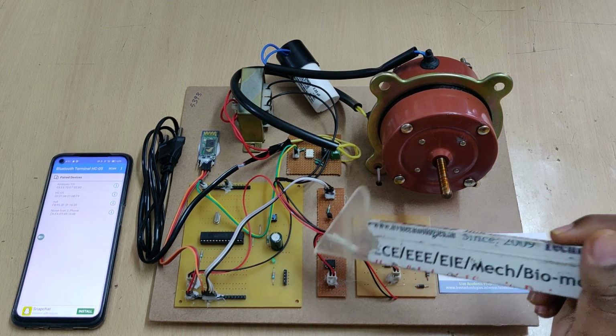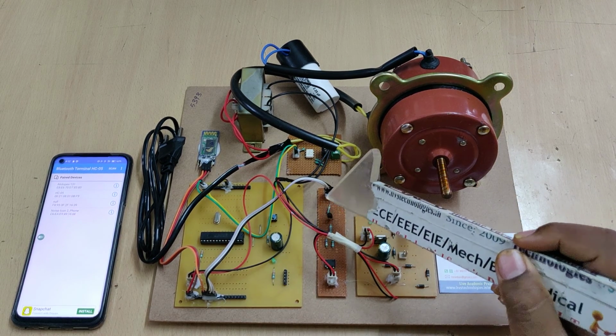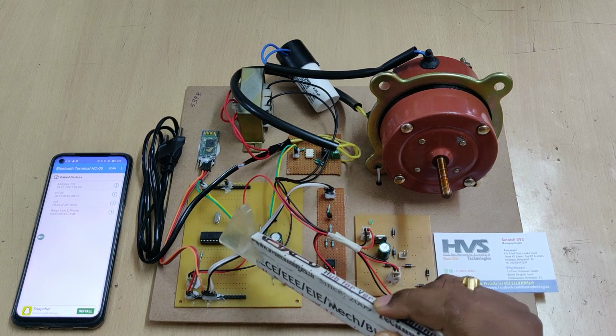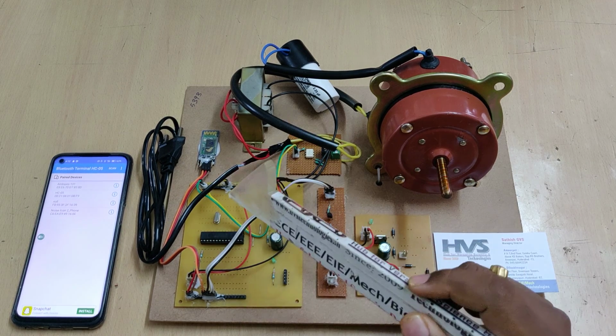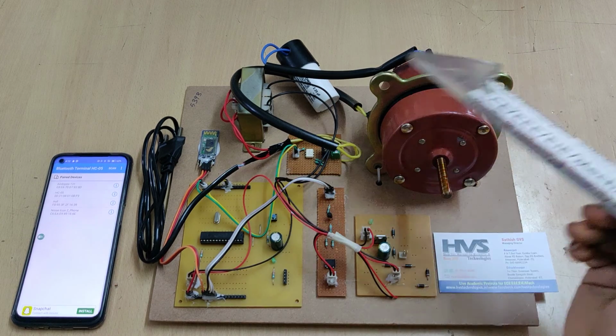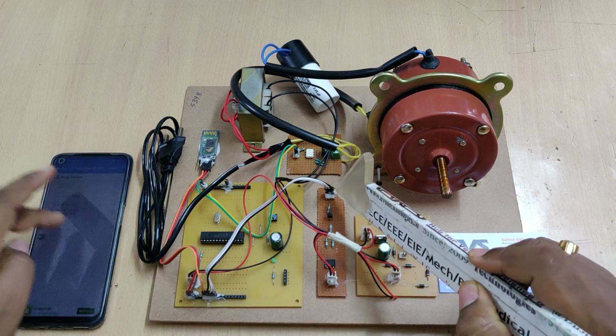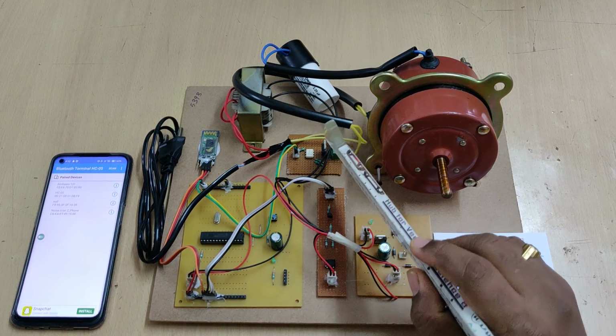Whenever the 12 volts AC waveform starts, the transistor gets switched on. So the controller comes to know that from there we need to regulate the voltage, which means we need to control the on time. When the zero crosses, the controller will take a decision to turn on the triac.